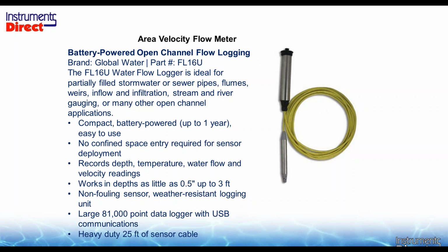The key here, a Manning equation is an equation that calculates how fast flow falls downhill, basically. And it's been around for a long, long time. Not as accurate as the area velocity method, but an I&I study is mostly about time. It's not instantaneous monitoring. So you can do this as a portable device, and you can buy these things for, I don't know, $1,200, something like that, as an alternative. And there's also dedicated versions of this. As I said, when you get less than 6 inches, your choices for doing open channel flow monitoring are limited.